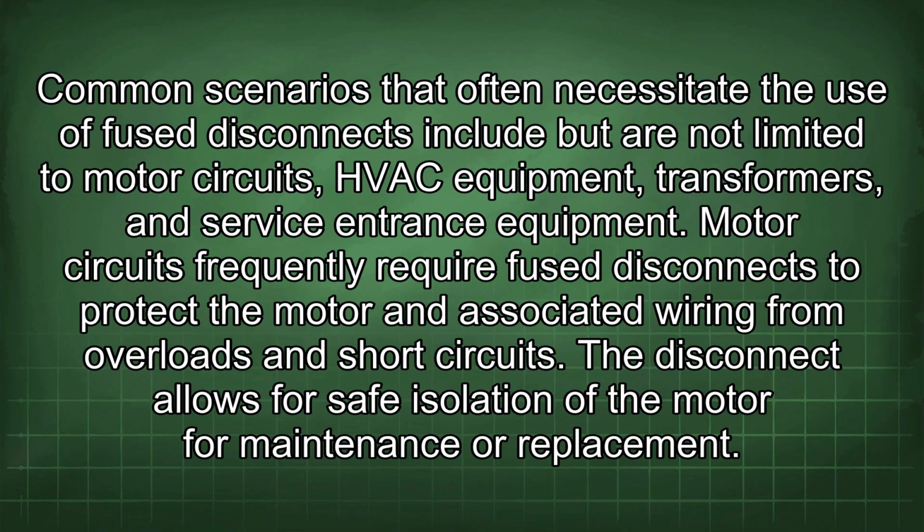Common scenarios that often necessitate the use of fuse disconnects include, but are not limited to, motor circuits, HVAC equipment, transformers, and service entrance equipment. Motor circuits frequently require fuse disconnects to protect the motor and associated wiring from overloads and short circuits. The disconnect allows for safe isolation of the motor for maintenance or replacement.